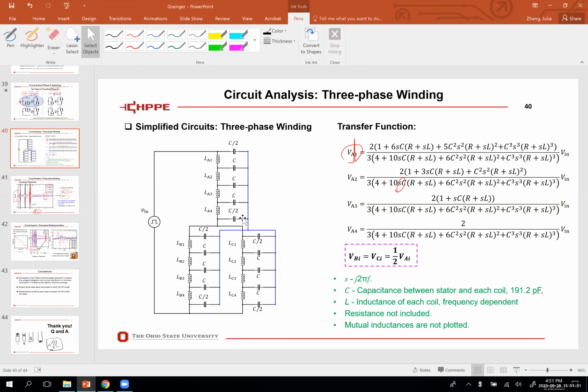Good. Maybe I'll ask one pointed question. What would you do differently in the next motor you build based on what you observed here? You brought up a good point about capacitance. We like to impregnate the windings, but you're pointing out that can make your capacitance higher, which may or may not be a problem. For me it's still a good thing, because maybe the first turn sees an elevated voltage, but the potted coil is more tolerant of stresses. I can imagine it leads to a lot of follow-on questions, like what are the right trade-offs? And maybe that's what you're seeing, that there's no one simple answer. I'm just curious.